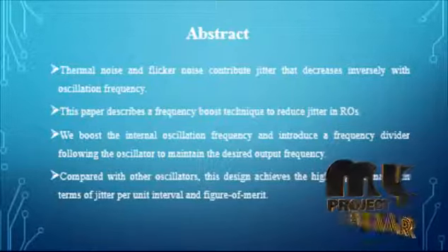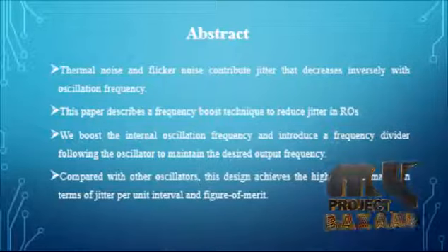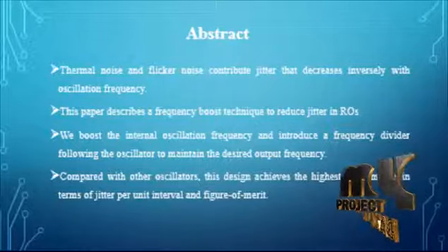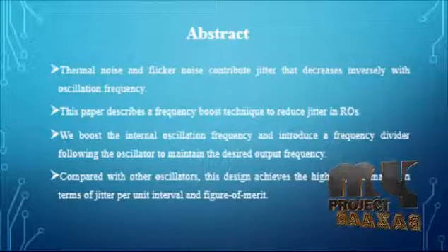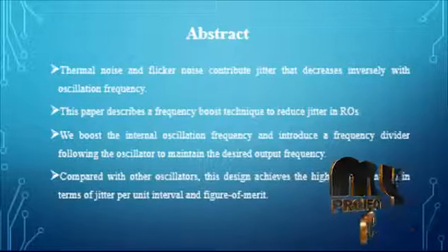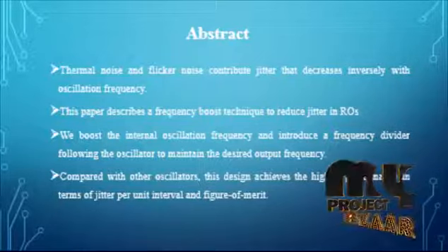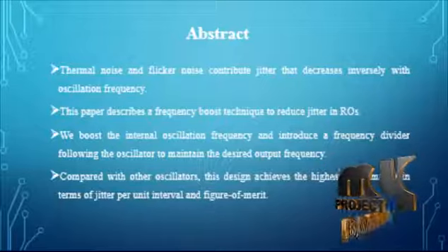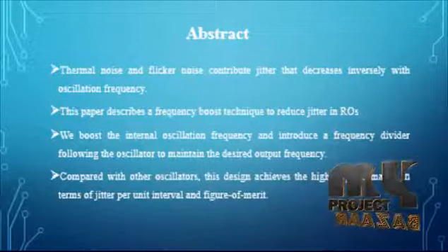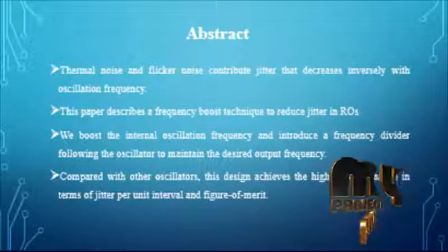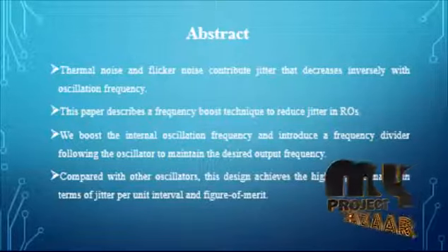Thermal noise and flicker noise contribute jitter that decreases inversely with oscillation frequency. This paper describes a frequency boost technique to reduce jitter in ring oscillators. We boost the internal oscillation frequency and introduce a frequency divider following the oscillator to maintain the desired output frequency. This approach offers reduced jitter as well as the opportunity to trade off output jitter with power for dynamic